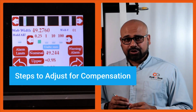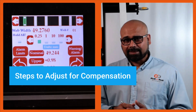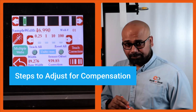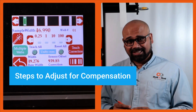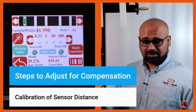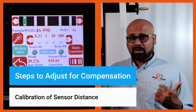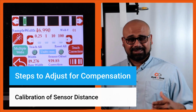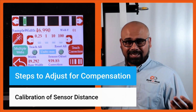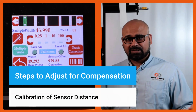One other thing we need to do whenever we are initially setting up is a one-time calibration procedure. That can be done on this screen. The idea for this is that we have the ability to calibrate our sensor for your conditions. We do have a calibration done in the factory, but when it's being installed, the sensor might be installed at a different distance than what we typically expect, and there are other things with the lighting and contrast that might change some of these parameters.